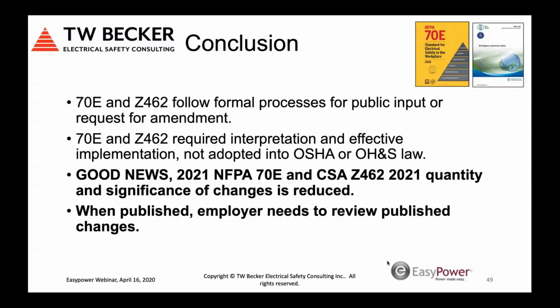And globally, this is really what we want to do: we want to make sure we use these standards, again, like I said, to the benefit of eliminating exposure to arc flash and shock hazards, or reducing risk to as low as reasonably practicable when energized electrical work is completed. We need energized electrical work to be completed by qualified persons. And in Canada, the US, and globally, it's trying to define that qualified person, which is a prerequisite and definitely a significant requirement to reduce risk with respect to likelihood of occurrence.